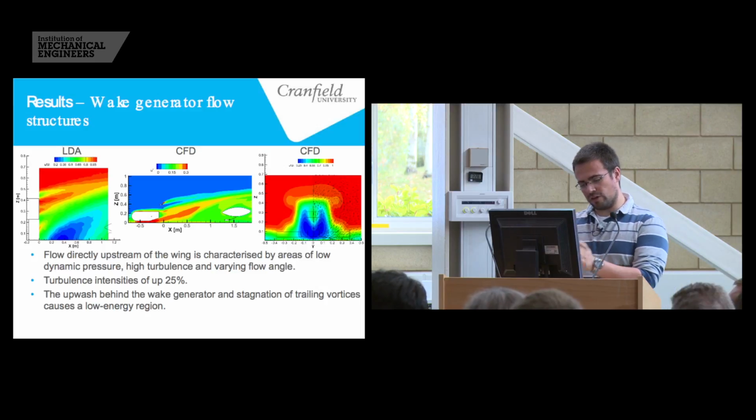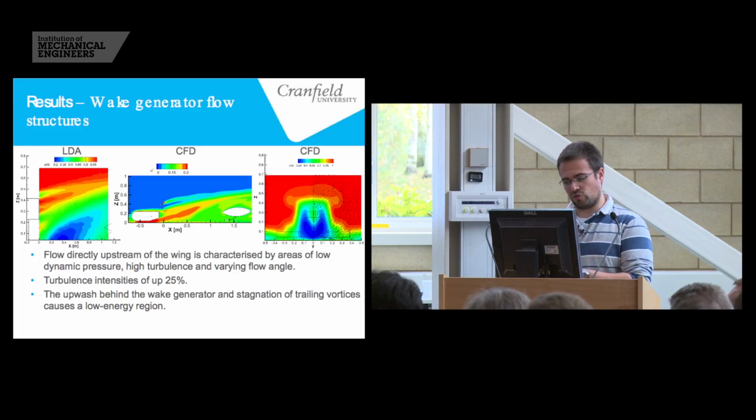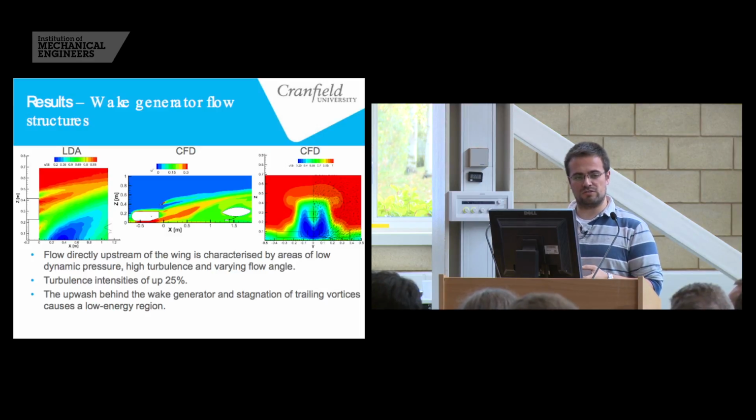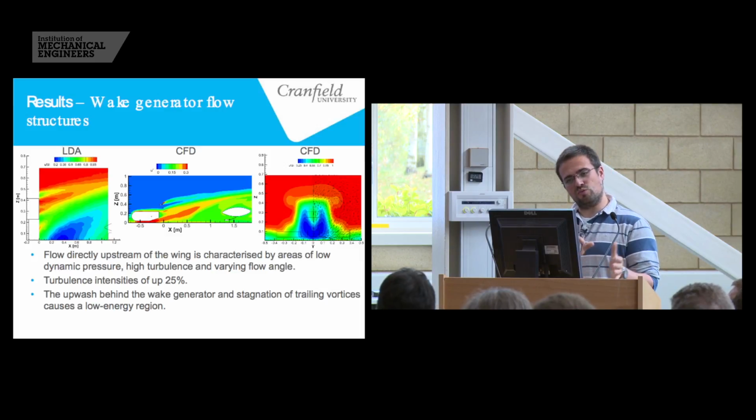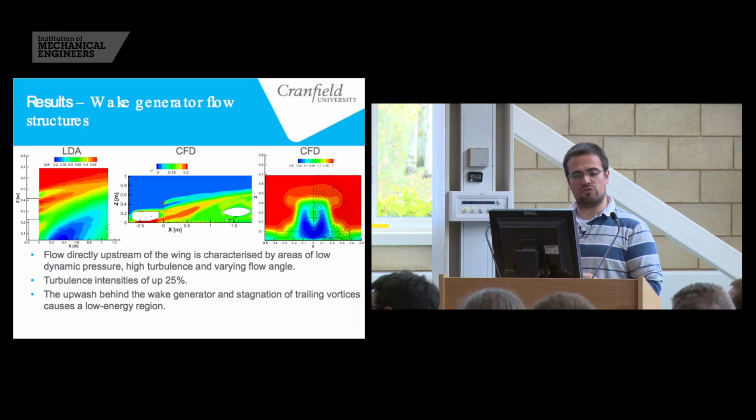But carrying on, looking at the vortex structures in the image on the left-hand side, I identified two different vortices, the main stronger one coming from the rear wing and a slightly smaller one coming from the diffuser at a quarter car's length separation. This shows up and doesn't show up in Joshua's work because my wing was further away from the diffuser. But when we move downstream, both vortices end up merging and we only have a pair of counter-rotating vortices.